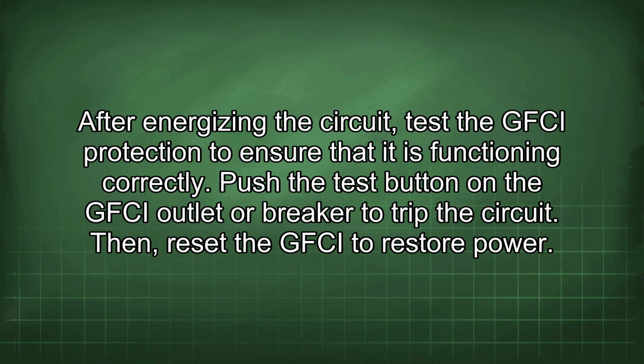Push the test button on the GFCI outlet or breaker to trip the circuit. Then reset the GFCI to restore power.